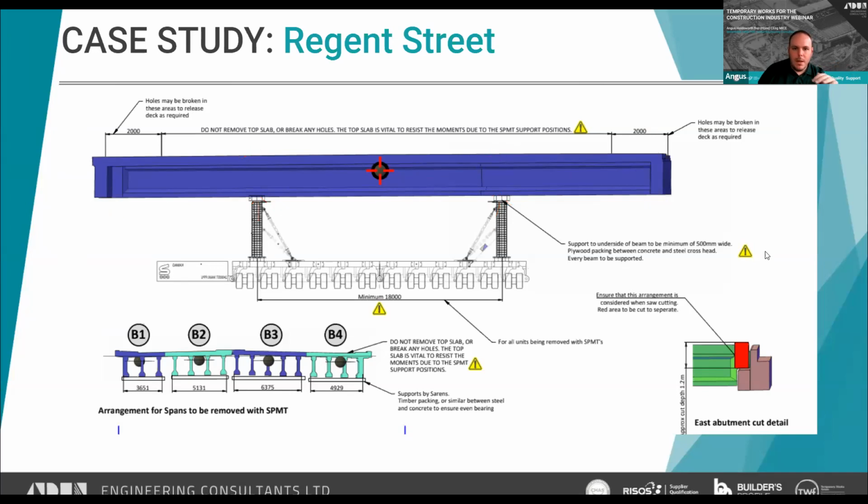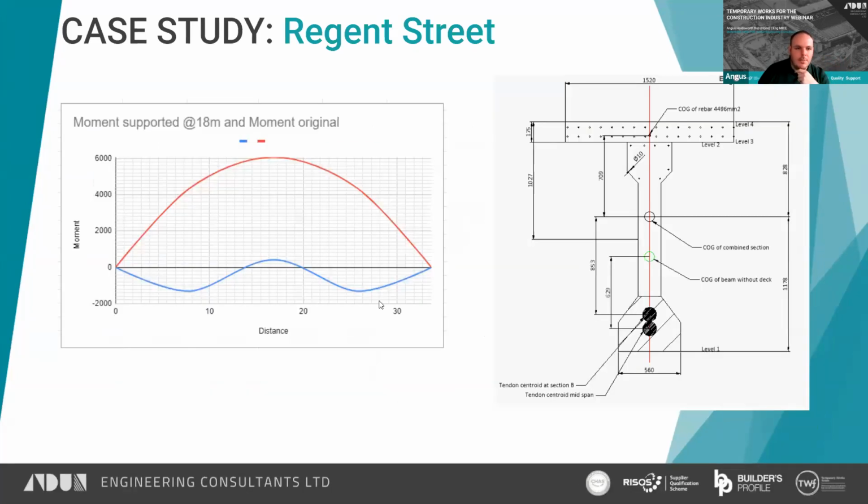So, there you go, put it out, so you've gone from a big sagging moment to one where you have a small sagging moment and quite large, well, fairly large hogging moments. This is the moment per beam. So load history again comes into play here, because you have to understand how the structure was built to understand the stresses in the structure in the current condition.